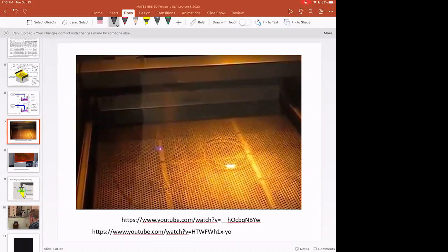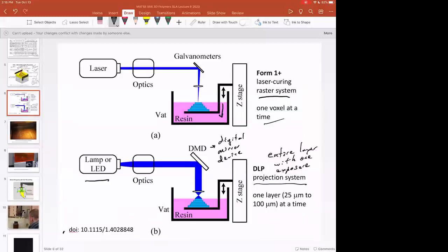And so what controls the layer height in this case is the distance between the wiper. So this is a wiper. Okay. And the solid part. You can't see the solid part because it's clear, but there's a solid part here, and the solid part is going to have a thin layer of resin right on the top.